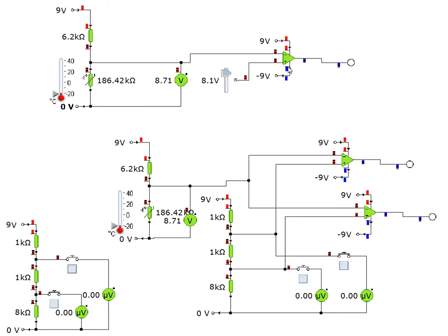At the minute, my non-inverting input has got 8.1 volts attached to it. The inverting input depends on the temperature. Just now, the temperature is low, and this voltage is quite big. So it's 8.1 at the non-inverting, 8.71 at the inverting one. So the inverting one is the highest of the two voltages, so the output goes low. It's minus 7 at the minute.